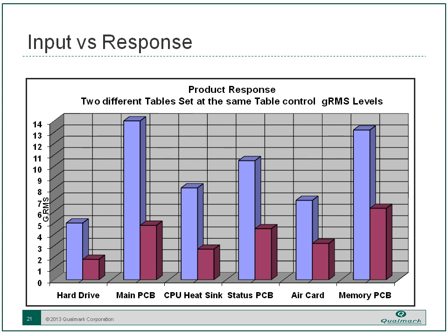It's very important that you monitor on the product. We say this in HALT a lot, and it's critical in HASS as well. Simply determining the set point in HALT that gives you the excitation that you need on the product, you can't transfer the set point directly. You have to be looking at the product to see how it's responding.